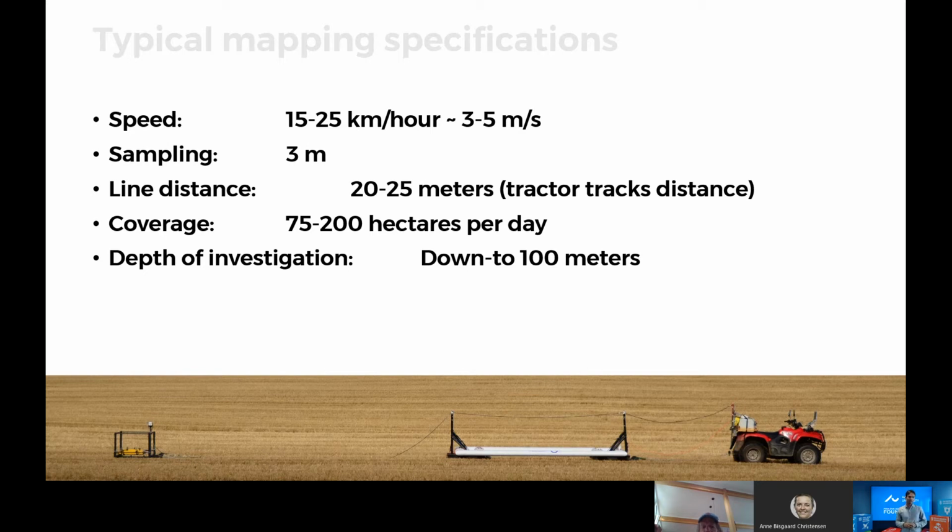That might take time. Depth of investigation is written here as down to 100 meters, but this system can be adapted to see more than 100 meters. For example, you can put one more turn in the system. This is a one-turn system, but if you put one more turn, you can increase the energy and retrieve the late time signals that correspond to the deeper part. So you can go 120 to 150 meters even.